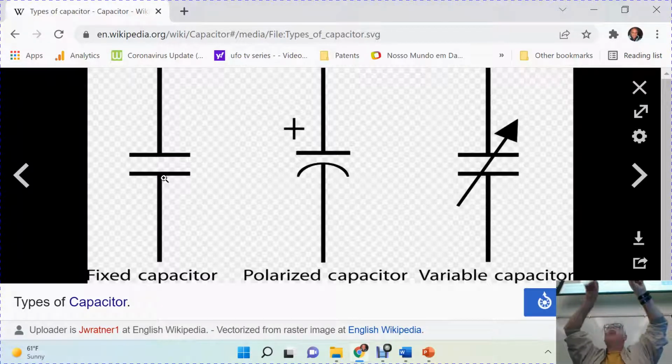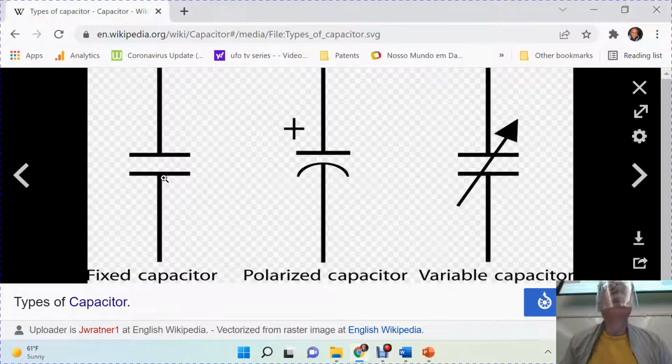I tell my students, don't connect the negative side to the positive of the battery. Most students comply, but then there's one or another group that connects the negative with the positive. They perform the experiment and the experiment doesn't work. When I investigate what happened, it's because you didn't charge the capacitor properly. And you have this risk: you can explode the whole thing. Not only damage, but also explode.